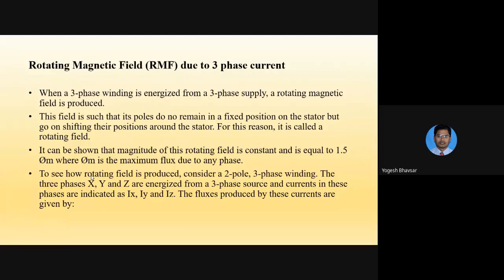Going into detail for the working principle of a three-phase induction motor, we first need to understand what a rotating magnetic field is. As the name suggests, whenever we give a three-phase supply to the stator winding, the stator winding produces a rotating magnetic field.